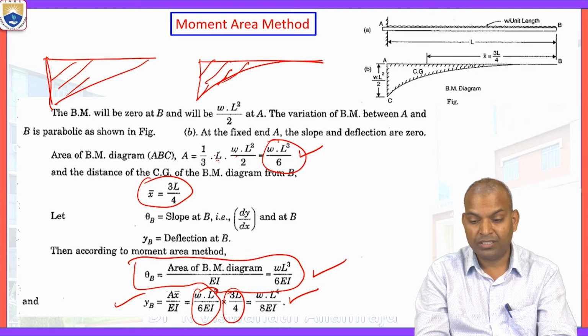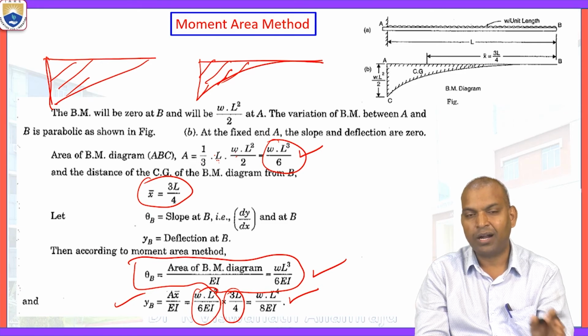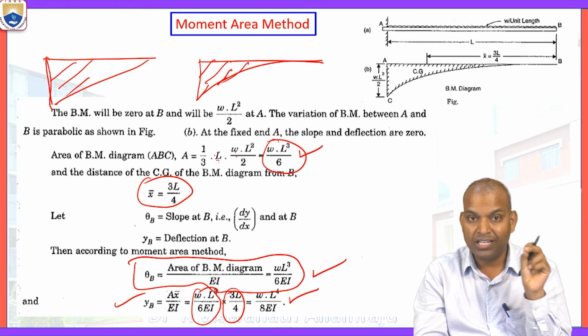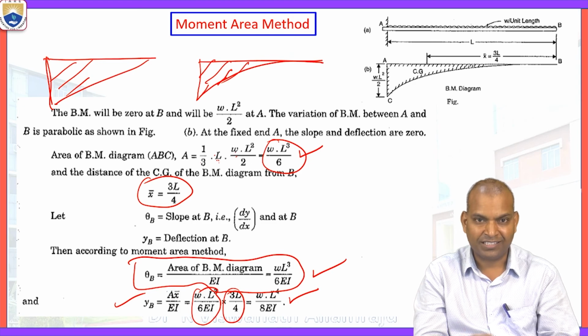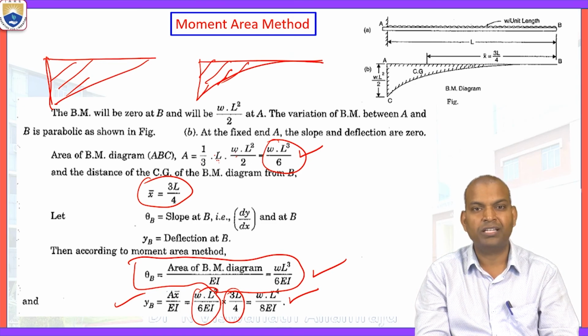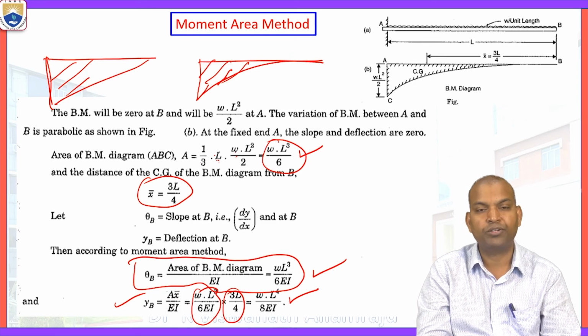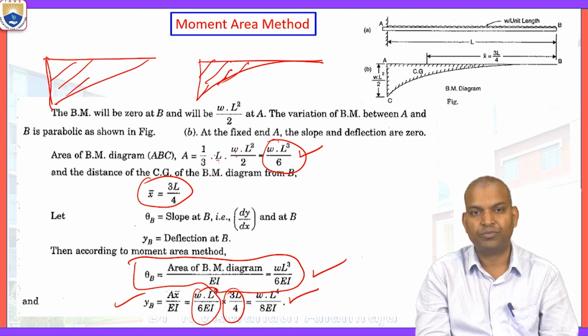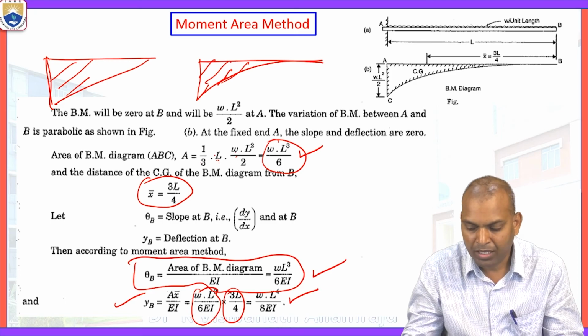It is simple, it's okay. For a cantilever beam, it is easy and mostly applicable. Whereas when multiple loads or combinations of loads are there, the total area required brings complexity. That is the challenging job for an engineer calculating the slope and deflections by the moment area method, in comparison to Macaulay's method and the double integration method.